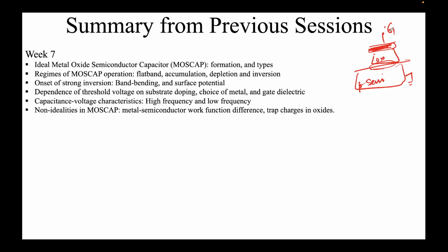If you apply the potential even higher, I'm going to draw it now in a different way. This is your Fermi level, and this is your oxide. This is the Fermi level over here, right? In the bulk, this is EF, this is EV, and it is still p-type, but at this oxide-semiconductor interface, the material has become n-type because EF is closer to EC.